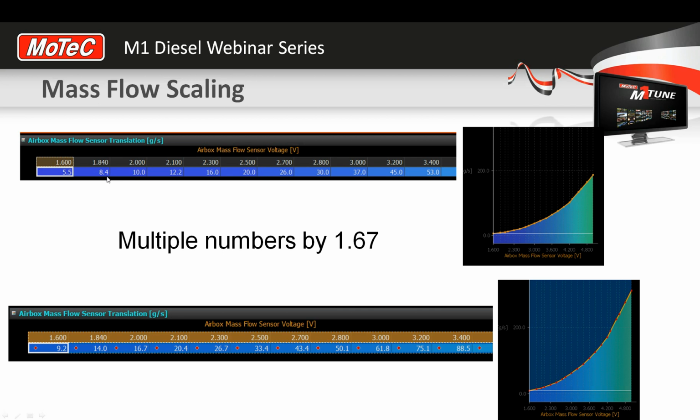There's really only a couple of ways. One of them is if you connect in series an airflow meter with a known calibration. You can simply go to each operating point in the engine's airflow range and observe what, say, the Bosch airflow meter says is the current grams per second, and then enter it in your calibration. So that's one way, and it's one method we use.